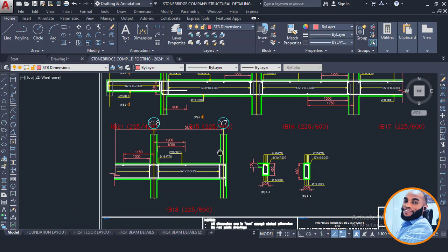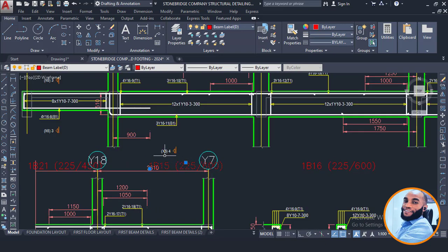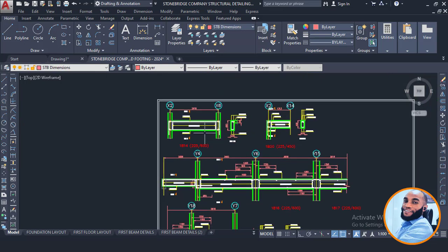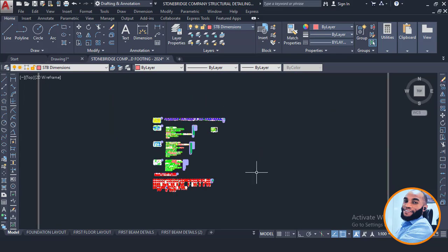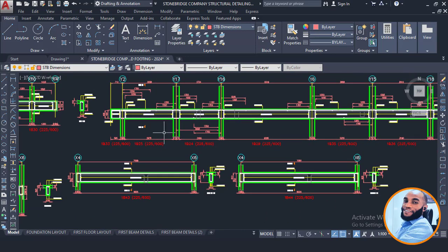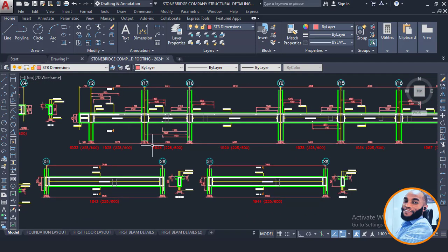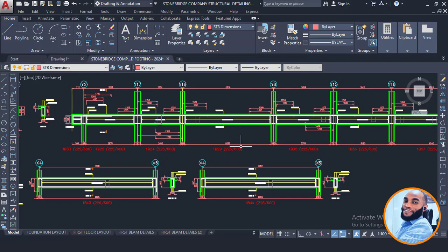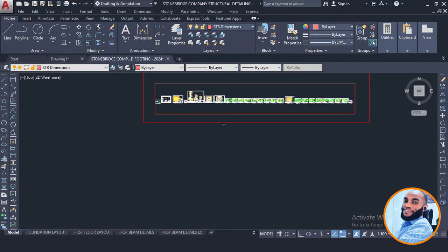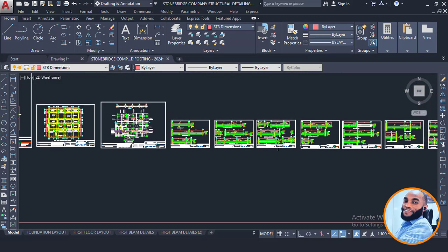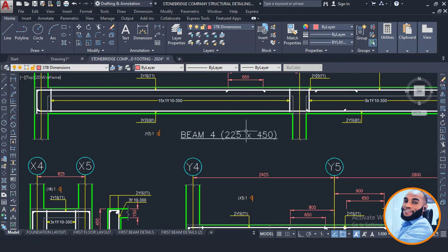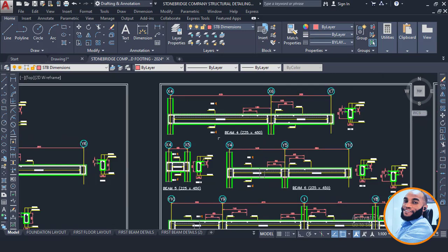Okay, so what I was saying, I have also made a video on how to name your beams. As you can see, this beam is not needed for you guys, and so I have trained on how to name your beam just perfectly like this. As you can see, this software Protastructure names based on panels, which is not okay for a continuous beam. A continuous beam is meant to be named as just one particular beam. As you can see on the sample of the Stonebridge template here, this is how to name your continuous beam. This continuous beam here is named just one beam, showing the size, not the other way around, where they will name here and here.